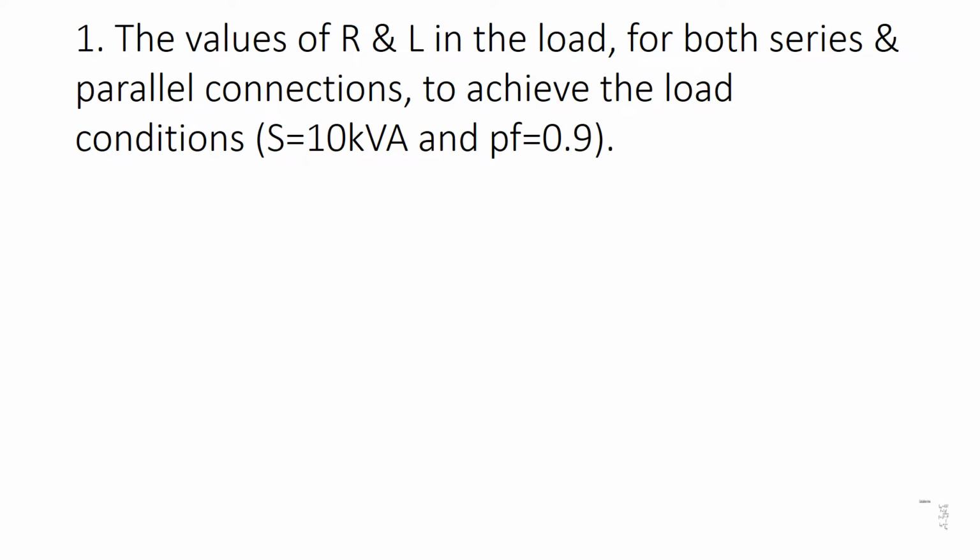The load conditions are given as S equal to 10 kVA and the power factor is 0.9. Remember, most of the time the given load is an inductive load, so this power factor of 0.9 is actually lagging, not leading.